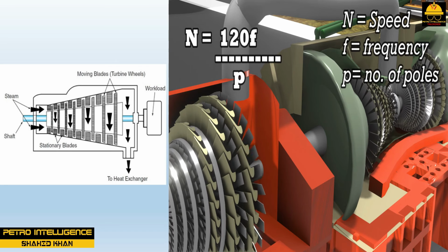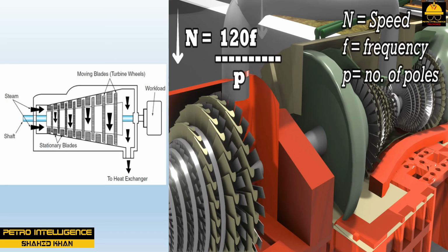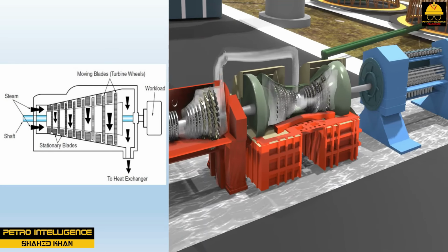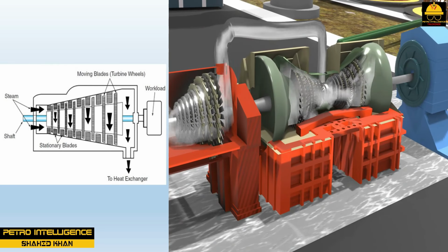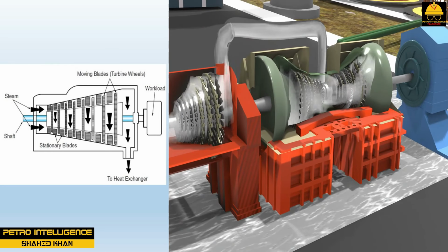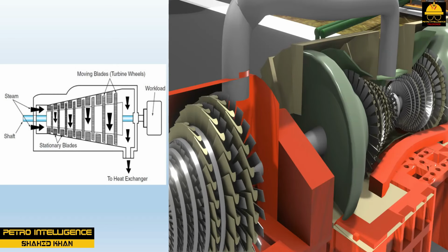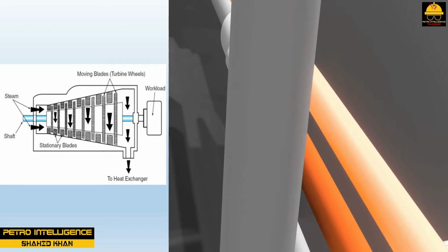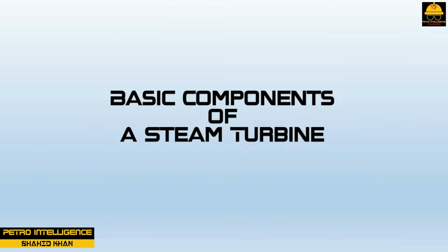As high-pressure, high-velocity steam passes over the turbine wheel, the steam expands. This expansion enables the turbine to divert low-pressure steam to other units. Some multi-stage turbines can induce steam into back stages to increase delivered horsepower. They are called induction-type turbines.